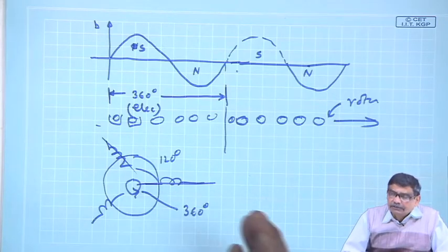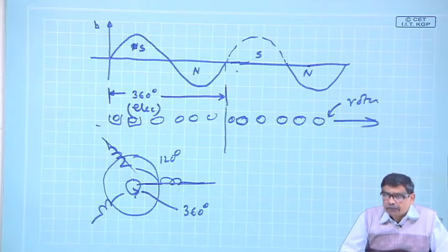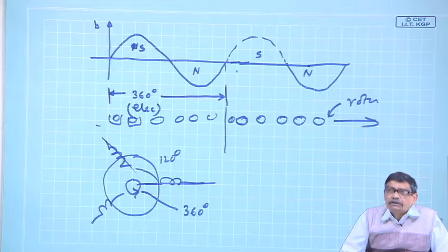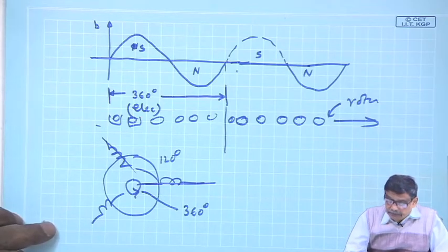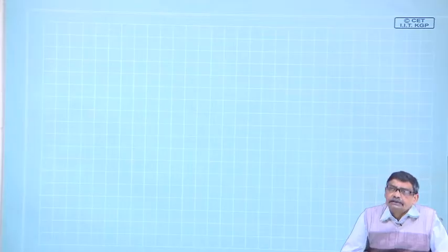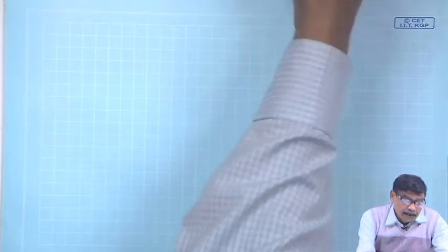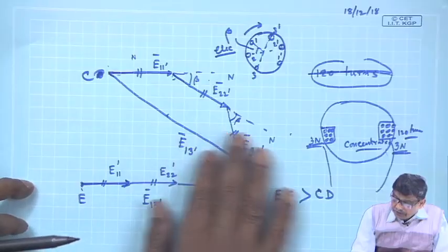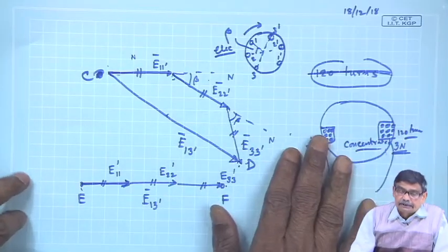because nothing is going to change in the next pair of poles for a given instant of time. That is one important thing, you note that. So, a multipolar machine is often represented as a 2-pole machine and all angles are shown electrical, that is all. You analyze that, that is it. Achha. Now, coming back where I left in the last class, that coils will be distributed or concentrated.